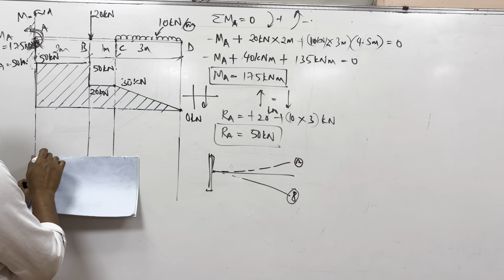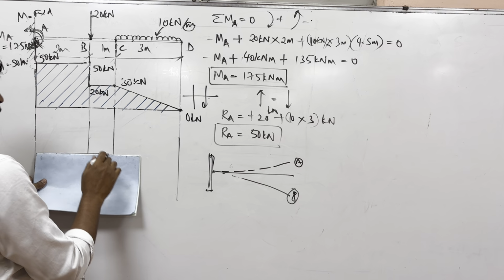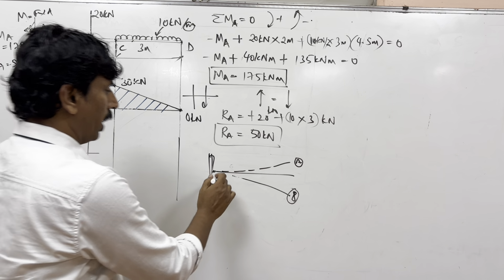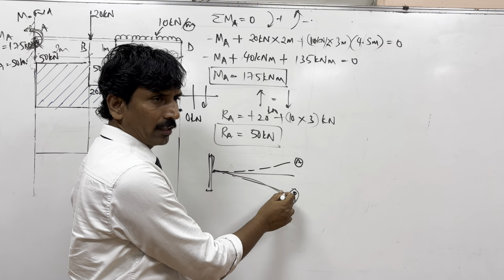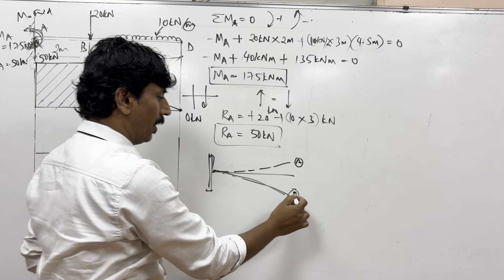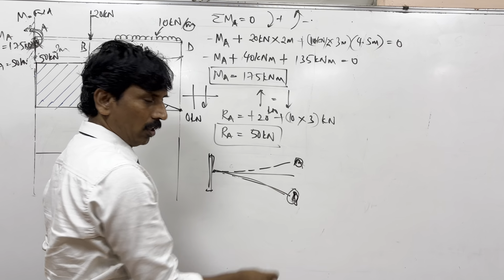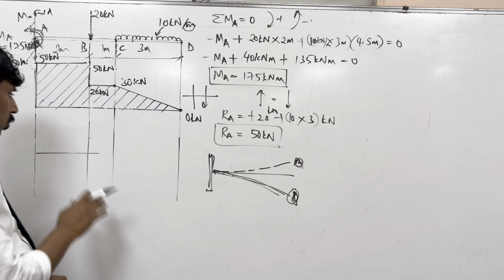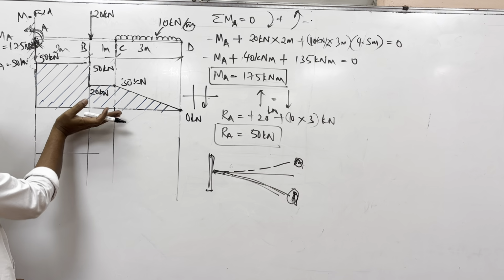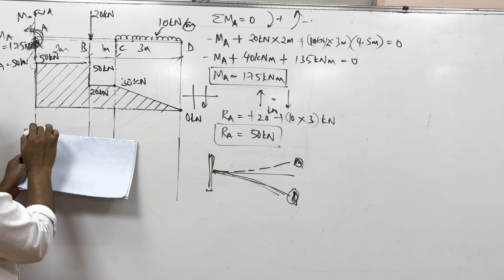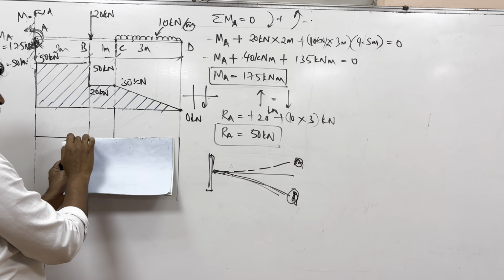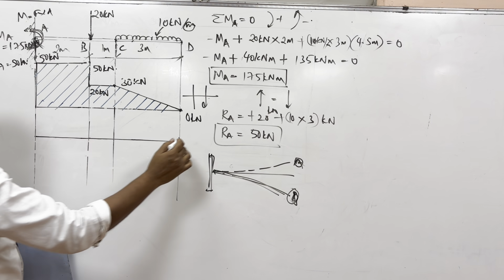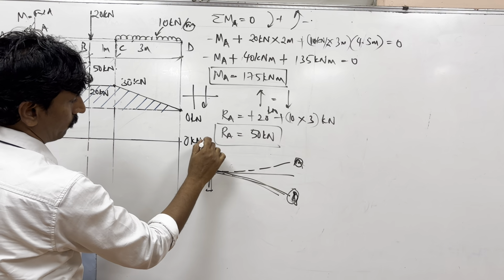Now to draw the bending moment diagram. We said throughout it will bend like this or like this. Will it bend like B or A? B. So that means it is hogging. Hogging means it will be negative. So if you have space above, that's useless. Therefore I will draw this zero line above itself, because now the whole diagram will come below. So 0 kilonewton meter.